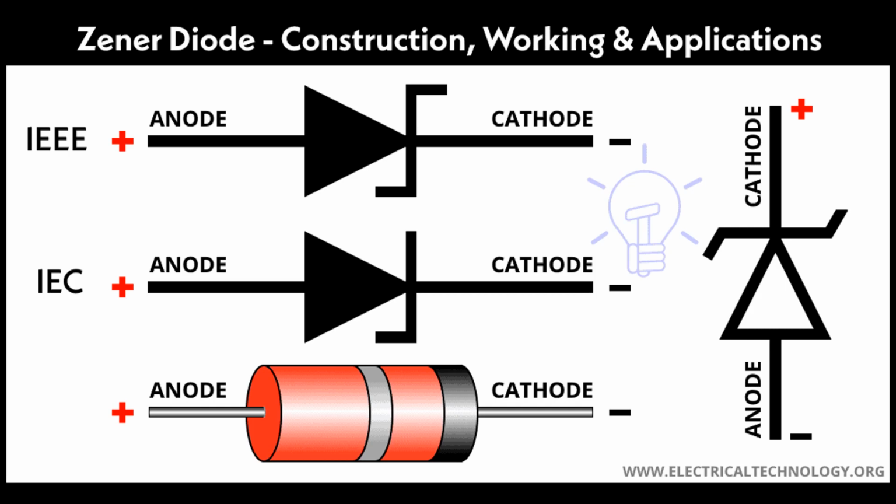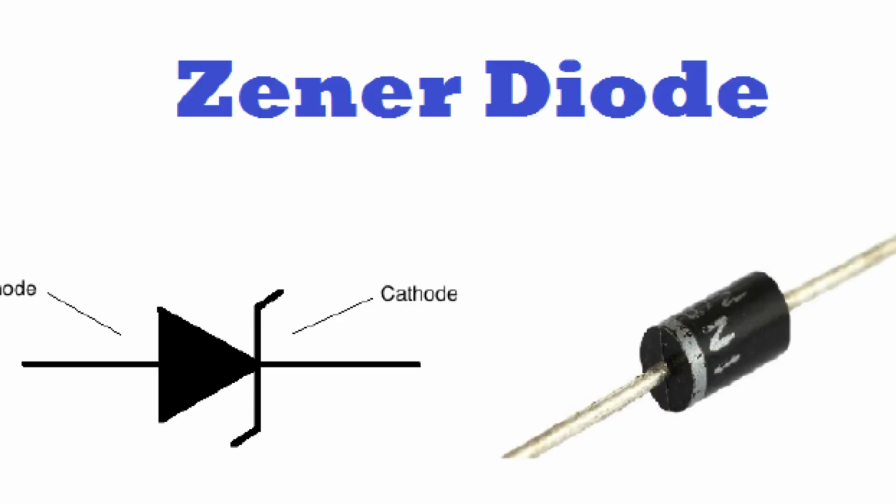Gas discharge tubes, GDTs, are devices that have a high breakdown voltage and low capacitance. They are used for high-energy overvoltage protection in applications such as power lines and communication systems. When the voltage exceeds the GDT's breakdown voltage, it forms a low resistance path for the surge current. Metal oxide varistors, MOVs, are components that have a nonlinear voltage-current characteristic. They have a high resistance at normal voltages but become highly conductive when exposed to excessive voltage transients.